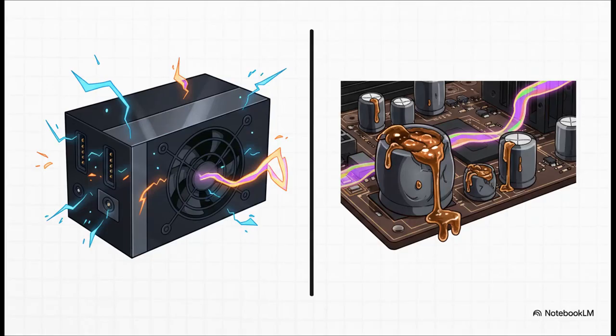So what are the usual suspects? Well, it could be your main power supply unit, your PSU, is starting to go bad. But honestly, a lot of the time, the problem's much closer to the port itself. See, the power for your USB ports gets filtered and regulated by tiny components right on the motherboard. If those little capacitors or voltage regulators are getting old and worn out, they can create ripple right there, even if your main PSU is working perfectly fine.